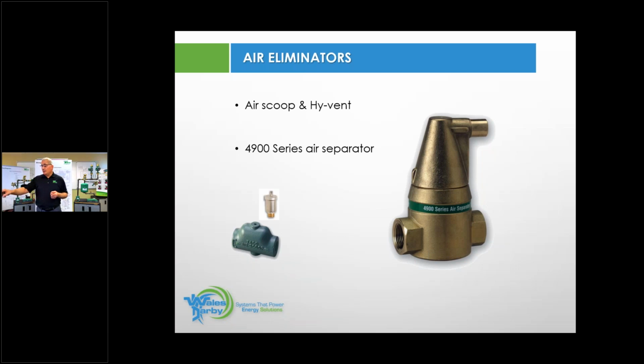We don't get leakers. You do have the ability to close the air vent once the system's been running and purged. You can close it, okay? So you don't need to put a metal cap on it or anything like that. There's just a little screw slot there, and you can close it up.